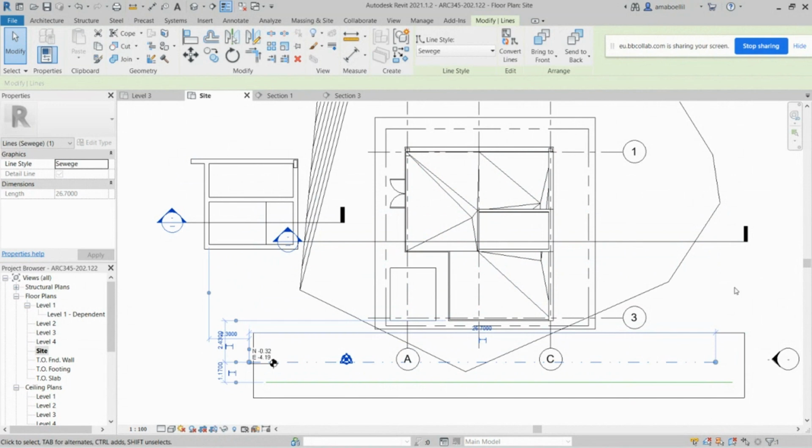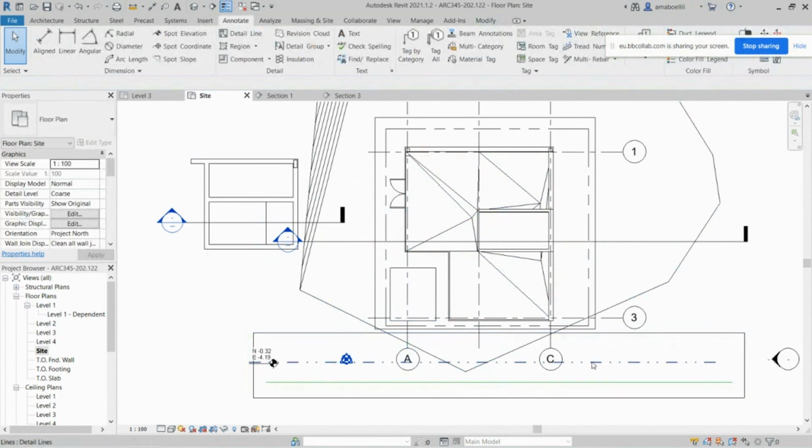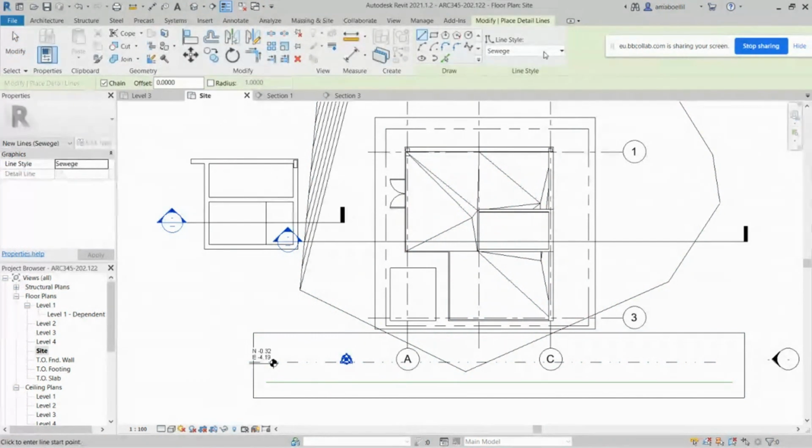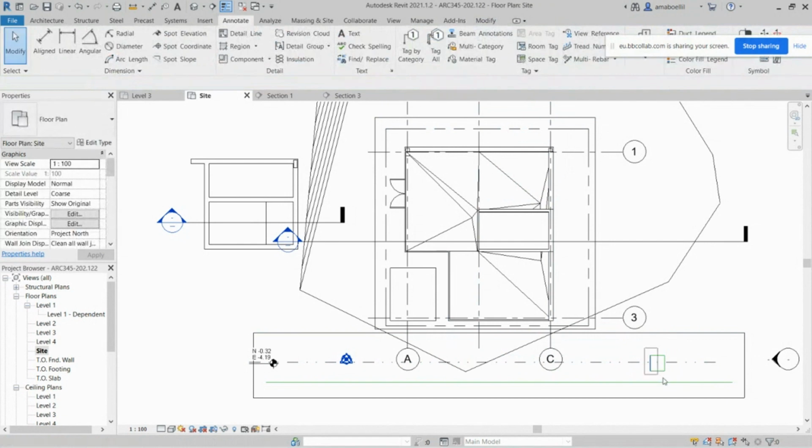So whenever any error, any problem, any leakage, any blockage, anything happens in that line, it can be exposed and checked. Feed that with manholes, which are the places where you get accessibility to the lines, and you can create those with little boxes, maybe by detail line. We can just go to line here and create these 60 by 60 at least. Once the line is green, you can adjust it as I showed you. Usually in each maybe 30 meters or so, you create one.